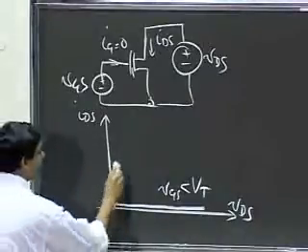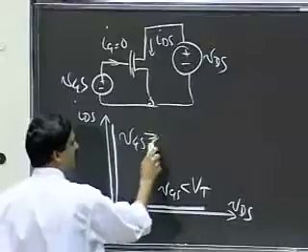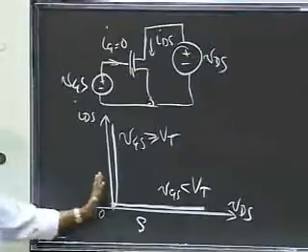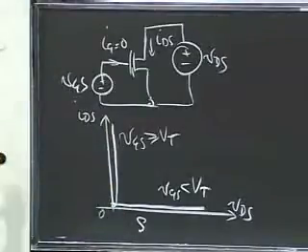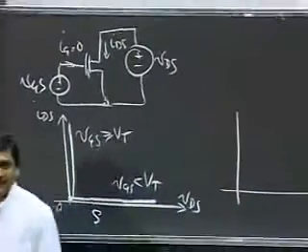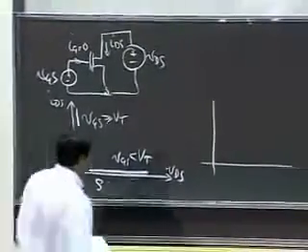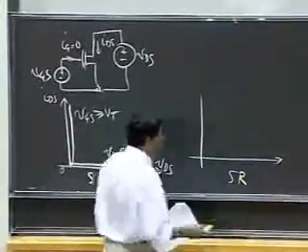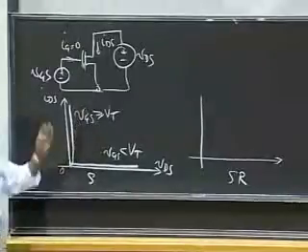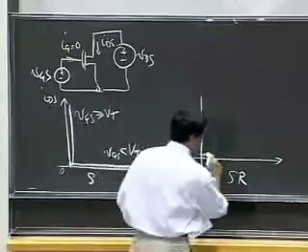And when VGS was greater than VT, the switch model of the MOSFET simply said that we can model the drain to source as a short circuit. You saw this in your labs, and you saw that it was a very small resistance between the drain and the source, and it kind of looked like a short circuit. But then we said, well, that's not quite it. There is some resistance, and so a slightly more accurate model would have this line droop a little bit to imply that there was some resistance R on between the drain and the source.